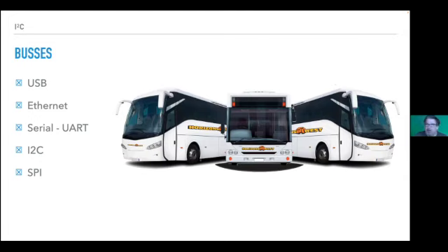So if I only talk to one, in that case, I only need the 3 pins because I can just tell it I always talk to that. But if I talk to 2, I need 5 pins. Talk one way, talk the other way, clock, and a pin for the one and a pin for the other, 5 pins. I'm talking to 3 chips, and I need 6 pins and so on.